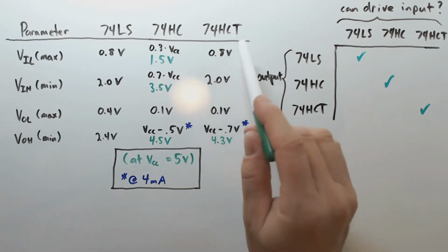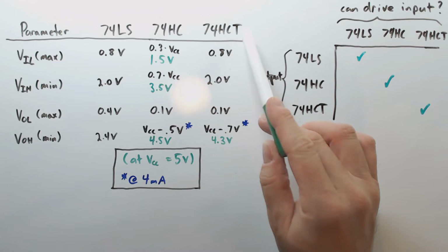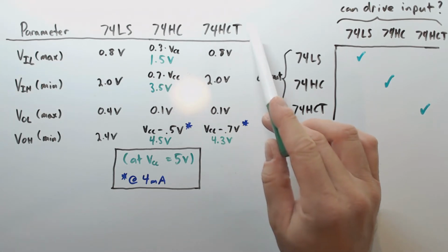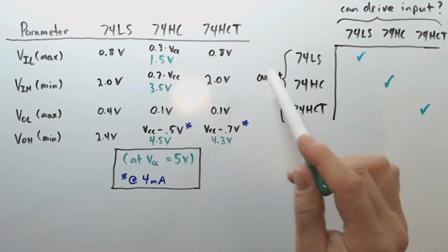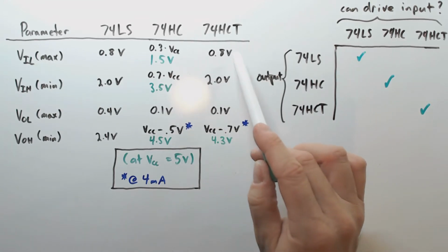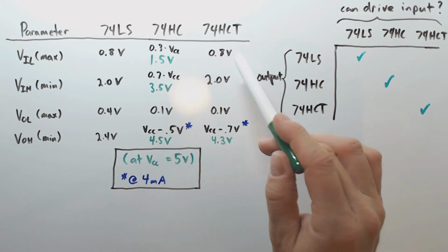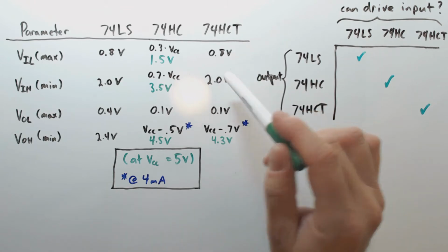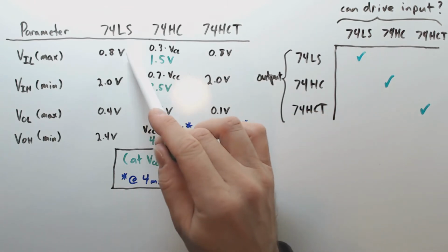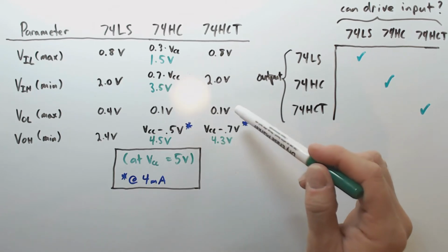Okay, so we'll talk about 74HCT series chips, and essentially these combine the best of both worlds. They are essentially CMOS devices and produce CMOS output levels. However, their inputs are compatible with TTL level outputs. So as you can see, the input thresholds for both low and high are exactly the same as 74LS. But the outputs are very similar to the HC series.